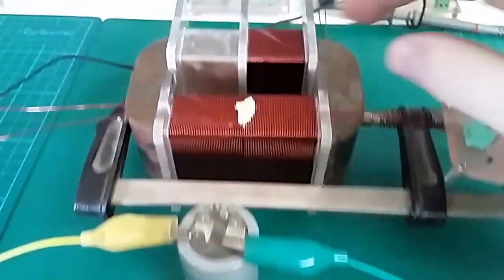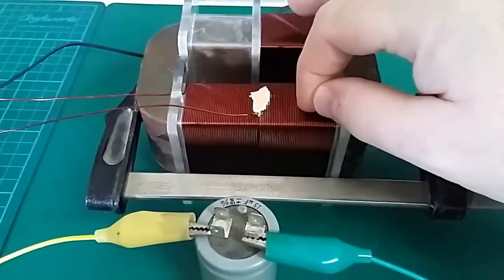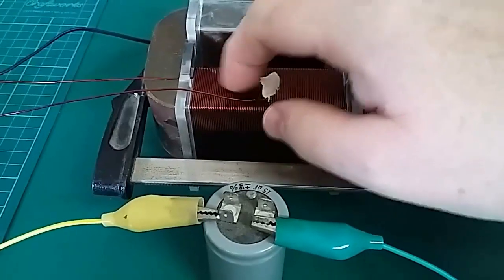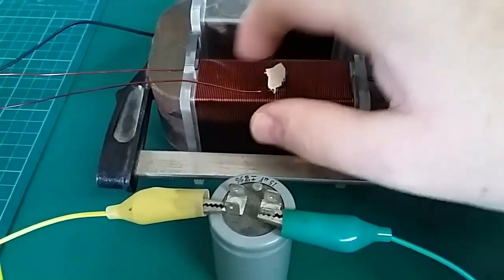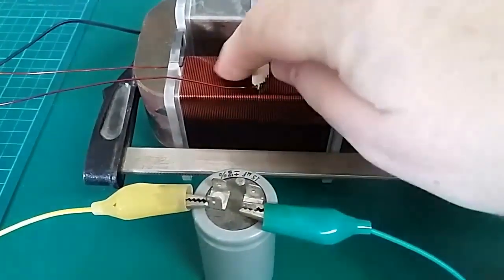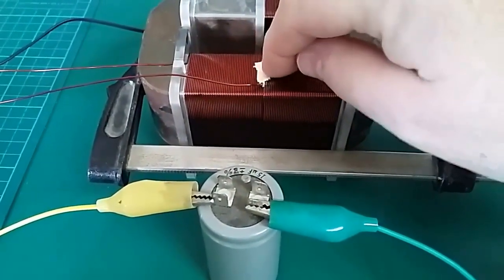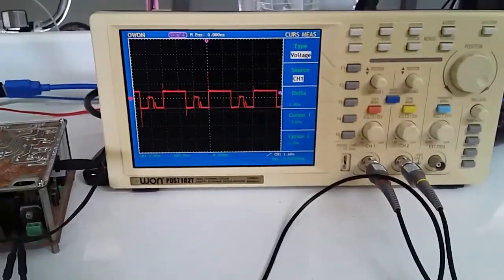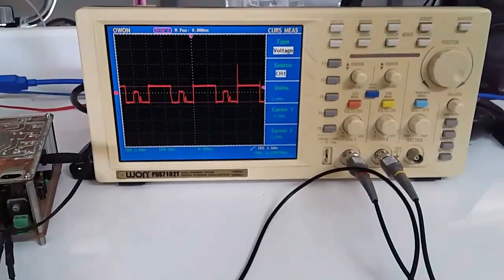The resonance that we've got on this particular coil over here, it's resonant with this coil, but it's not resonant so much with this coil. The inductance versus the capacitance, the resonance here is not ideal, and that is because of the inductance difference again. So we've got a little bit of work to do. We need to find out why the reflection's coming back.